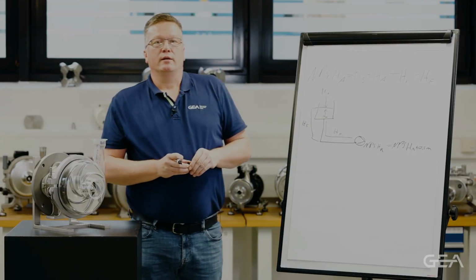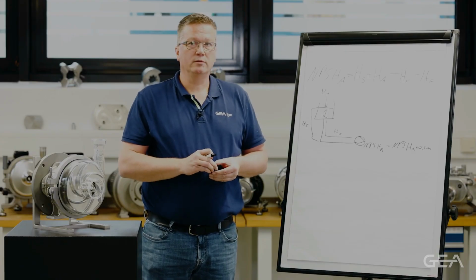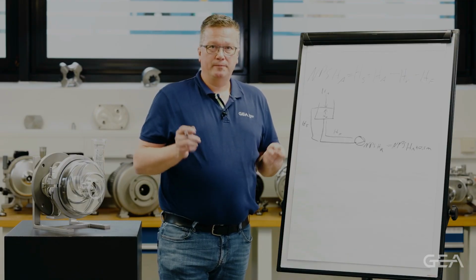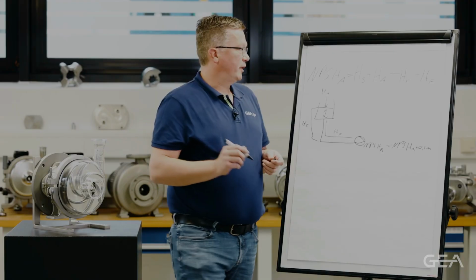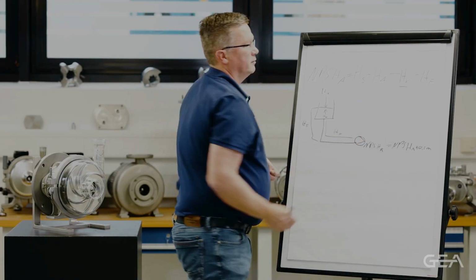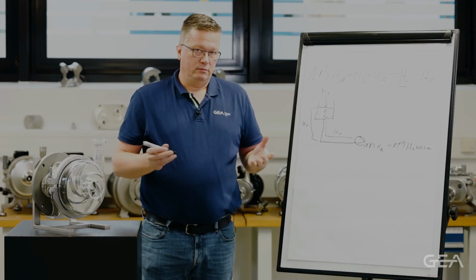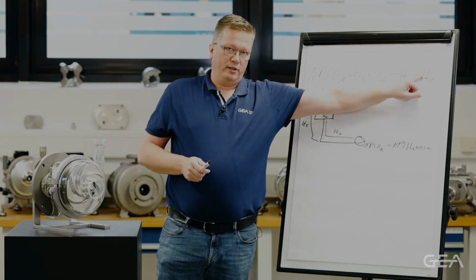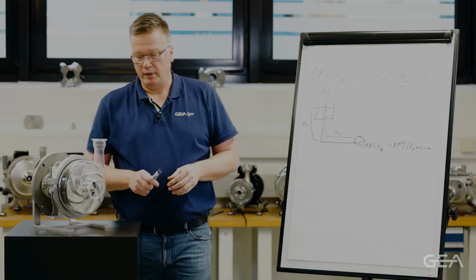Vapor pressure can change the complete calculation dramatically, because for water, for example, at 20 degrees, we have a vapor pressure of 0.23 meters. If we heat it up to 90 degrees, we have 7 meters. So then you change this factor dramatically and you come into the NPSH problem value. And this is not what we want to have. Also, the friction losses need to be calculated.